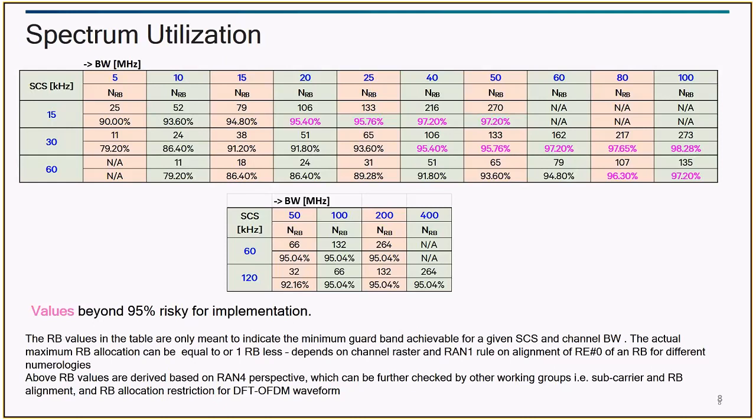So this is for a handover case, you are saying? No, even this is initial access. Initial acquisition. The problem is we don't know the bandwidth. The first specification is non-standalone, wherein you would always camp on LTE, initiate a call on LTE, get a data and IMS bearer attached on LTE, and you are configured for a measurement of an NR channel.